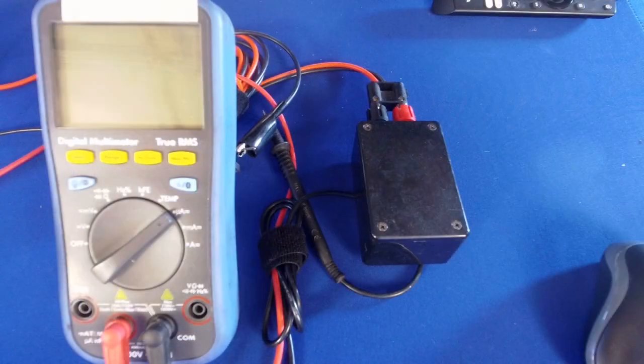You can use this and go read individual isolated devices like a relay, a smoke, a single module, a double module. Now, relays usually read about 140 microamps. The newer ones read about 40. They've improved the circuit, and it uses less current. Your smokes are about 300 microamps. Your single modules are right around 250 microamps. Your double modules are right around 450 microamps.